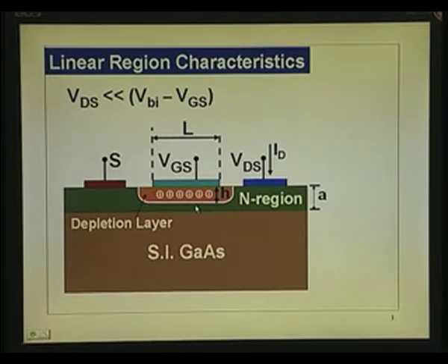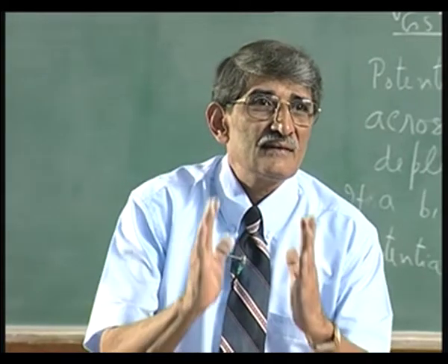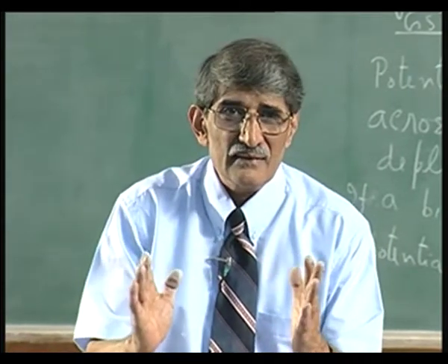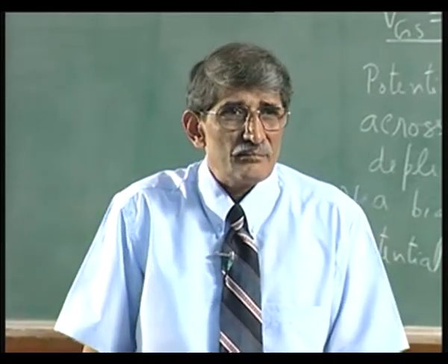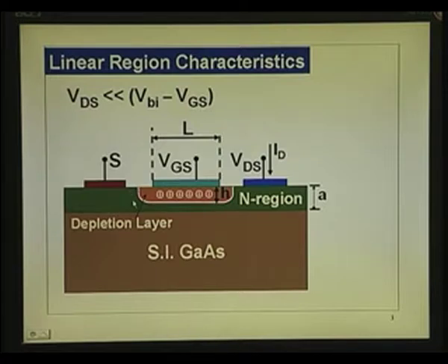When you write all the equations, when we say VDS, it is just across the channel length. We are not considering the drops beyond that point; that you can add as IR drop, because this portion's thickness is not changing. It is a constant resistance that you can add up later if you want to. And if you bring this contact closer and closer to this, the drop becomes smaller. This aspect we will see later, how to bring it closer together and what impact it has on the IV characteristics, that has to be seen in the practical device.